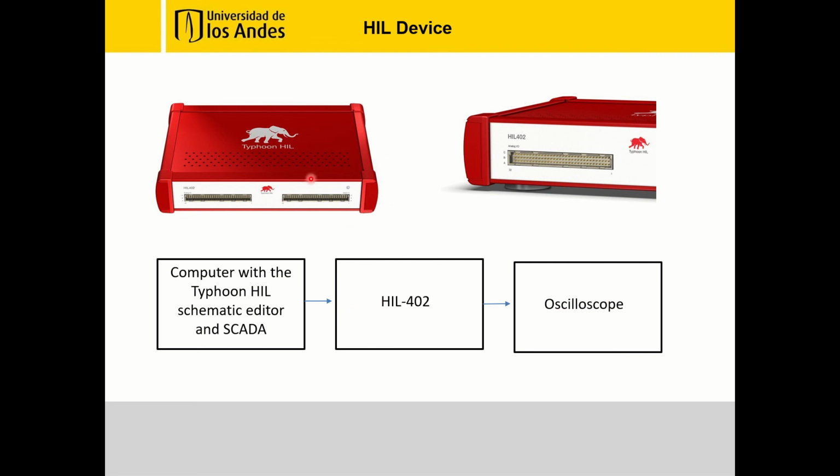Firstly, let's observe this image right here, where two output ports can be seen. There's the analog and there's the digital output, and in this next image there's a close-up on the analog output. Here we can see three labeled pin rows. The most upper one is C, which is the ground connection, and then B and A are for data. The oscilloscope comes with two probes. One was connected to the most left connector, which corresponds to A0, and the other one was connected to the pin to its left, which is A1. Later in this video, we will show the oscilloscope readings to see the final signals.